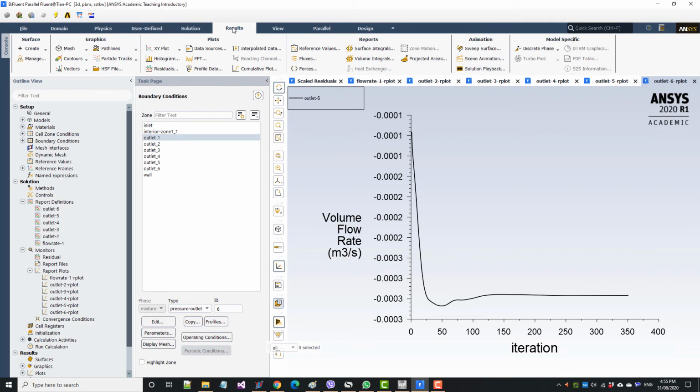First, let's look at the mass balance and remember that this is in the Reports group under Fluxes. We will go to the Results tab to view the solution. Over the course, you will learn about many post-processing features available in the Results tab. Here I only want to show you a couple of things, namely how to show mass balance and how to plot a path line flow profile.